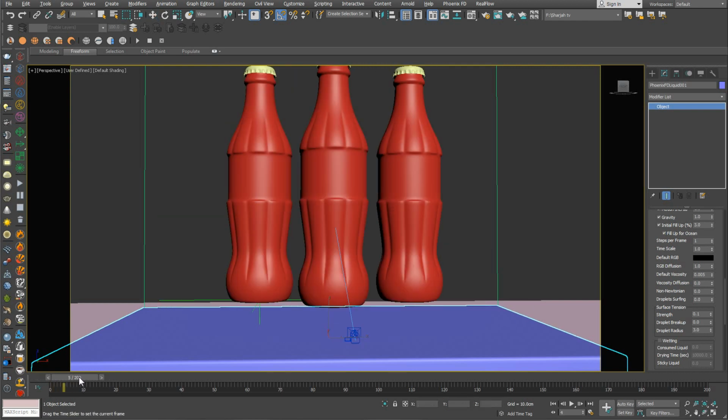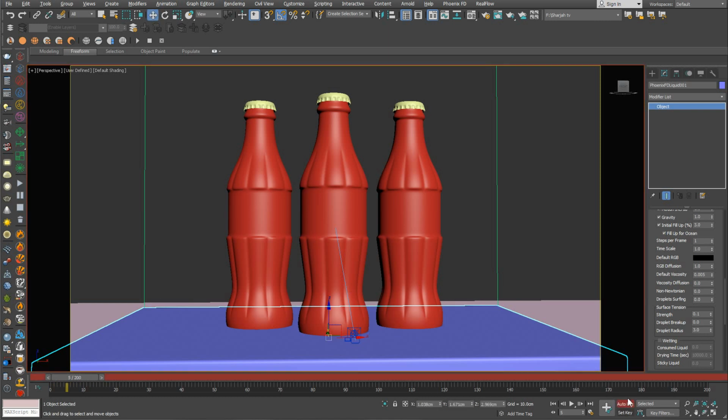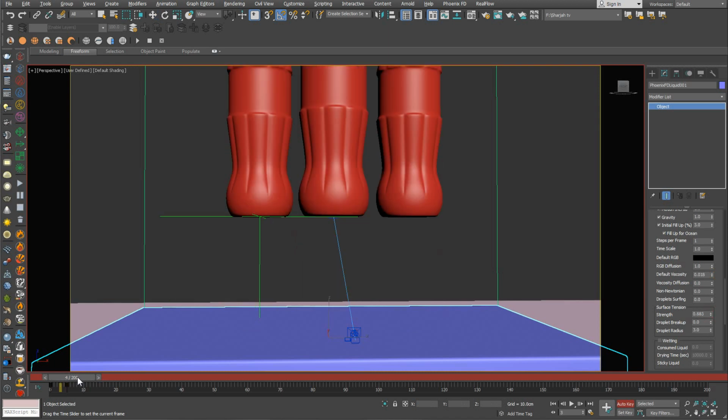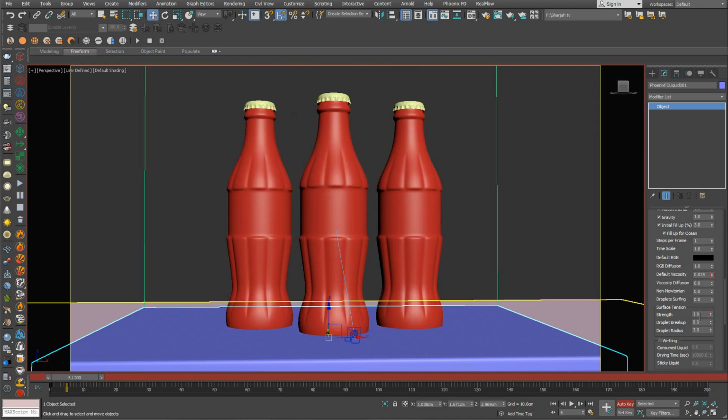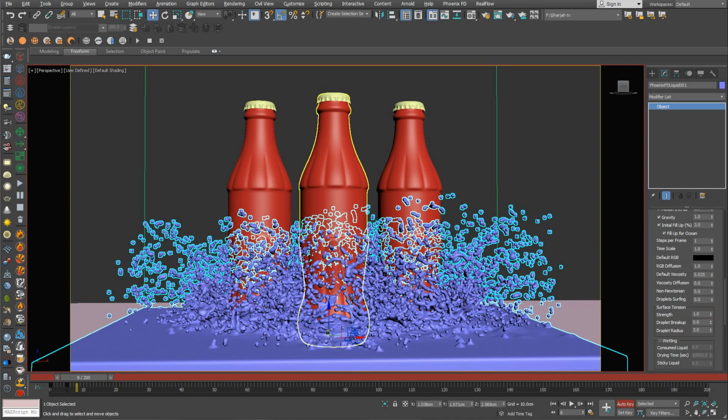Let's jump to the fifth frame, and here I can introduce different numbers for both. I can increase this, let's say, 5 times, and also increase this to 1. What I'm doing now is that when the collision is happening here, I want the surface tension to be very strong, which will not allow the particles to break up or just move separately.